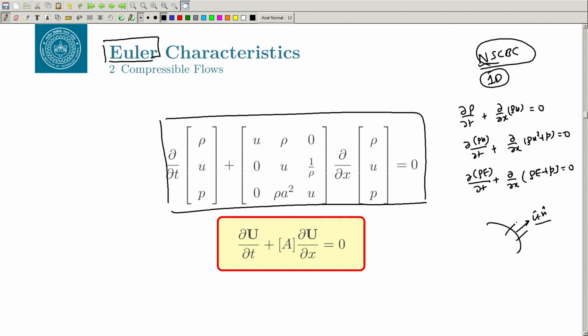Okay, so as we saw, that gives you whether it is inflow or outflow. So, we will basically be interested in u perpendicular, and then you can make a local 1D assumption there and implement all these equations, right. So, if you expand it, this will become dρ/dt plus ρ du/dx plus u ∂ρ/∂x equals 0, which is what is written here. You can see this u ∂ρ/∂x is given here, and then ρ du/dx. So, this is your first equation.